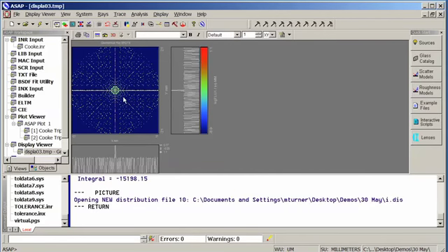Now you might say that this is the on-axis performance and what we're seeing is the effects of spherical aberration, but notice the size of this detector. It's 42 millimeters on a side. This is the full size of the detector. Here's our on-axis image, and all of these other hits indicate other ray paths through our optical system other than our desired path. And what we might want to do is analyze how light, in this case, either makes it to our detector or makes it through our optical system as a whole.